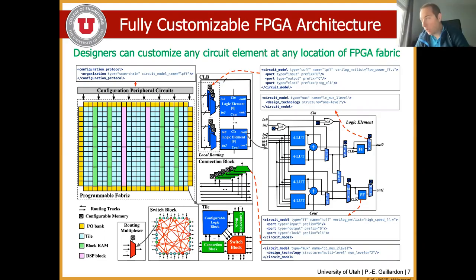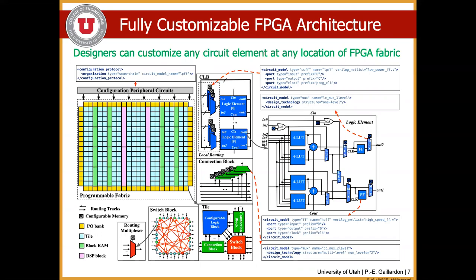That's right. Actually, we're not really using the Yosys ABC tech map. What we do is use Yosys for behavioral synthesis, passing everything to LSOracle to handle further levels of optimization with MIGs and AIGs. And as part of that, we have our own tech map on MIGs and the ABC tech map on AIGs that we bring back together. But same principle. FlowMap-like tech mapper, stuff like that. So, okay. Yeah.